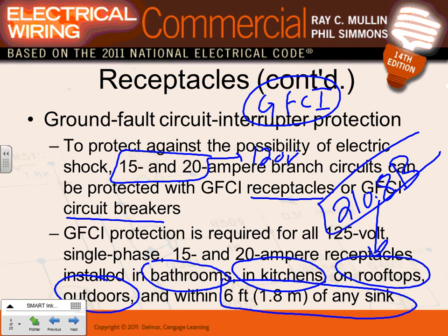A lunchroom becomes a kitchen if you have a sink and a permanent place to prepare food. A permanently installed microwave constitutes a permanent place to cook, right? So you have to have a countertop sink, and a permanently installed range or a permanently installed countertop microwave or whatever. That's how it's constituted.